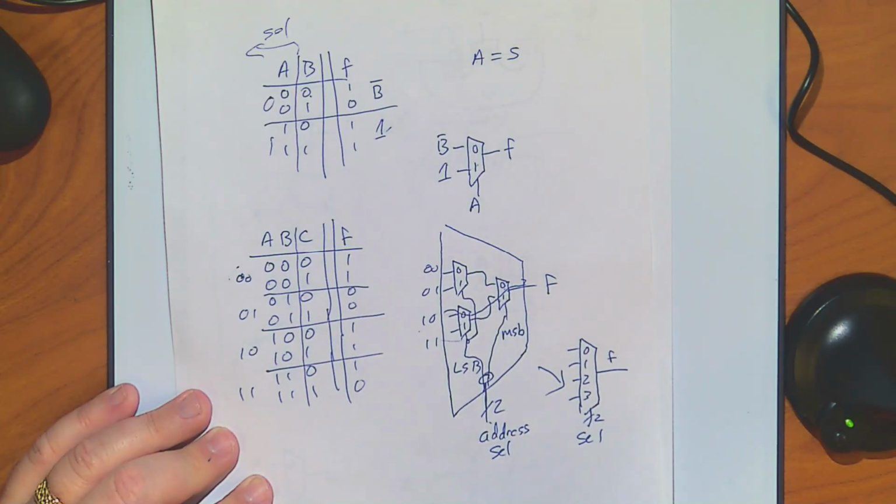But you nest a whole bunch of these, and these also become a case statement. So if you build a case statement or a bunch of nested if-thens, it's going to be transmission gates very efficiently. And remember, that was really common for us.